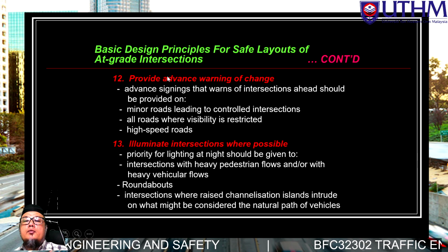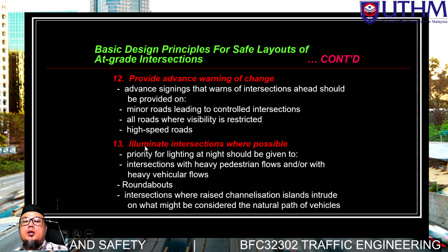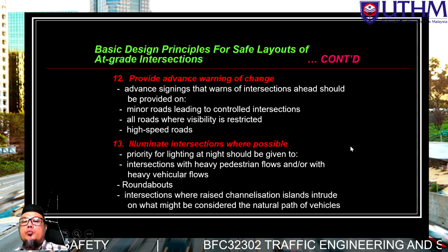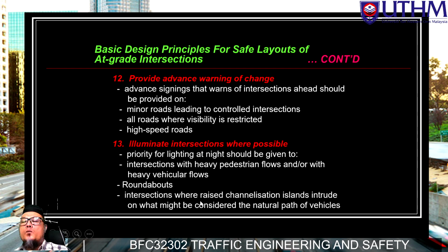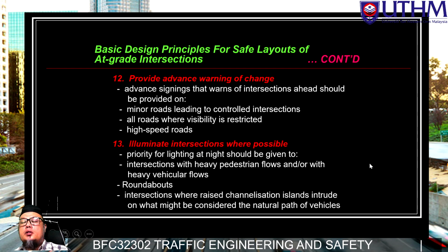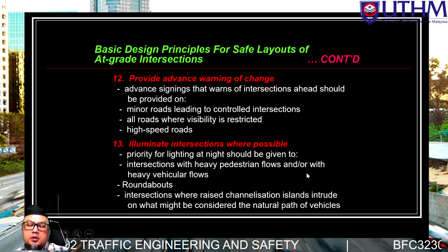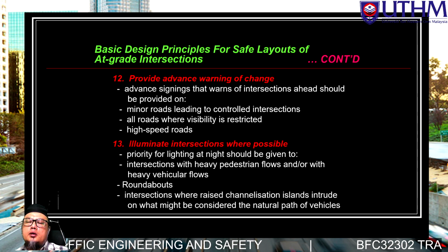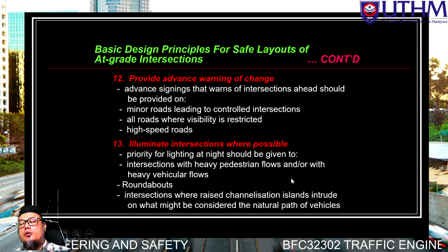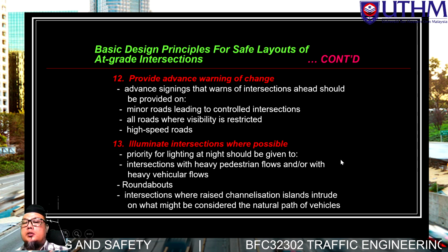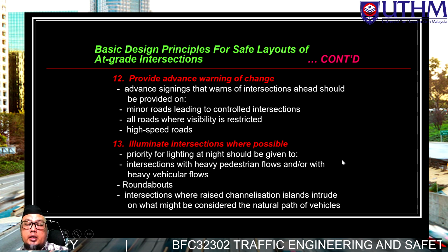Okay, number 12, provide advance warning of change. Okay, 13, I think the last one, illuminate the intersection where possible. Sometimes the location of the intersection does not have enough lighting or illumination, especially where there is a dense pedestrian population and activities. Sometimes we have to provide enough illumination to give proper vision at night time.